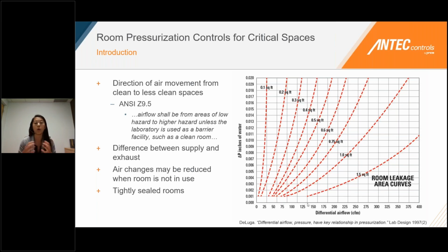that small open area. So again, just something to keep in mind: perfectly tightly sealed rooms are very difficult to accomplish in design. Most of the time, some of them will still have a little bit of leakage, which is typically acceptable. You just want to account for that in your offset calculations or your airflow calculations.